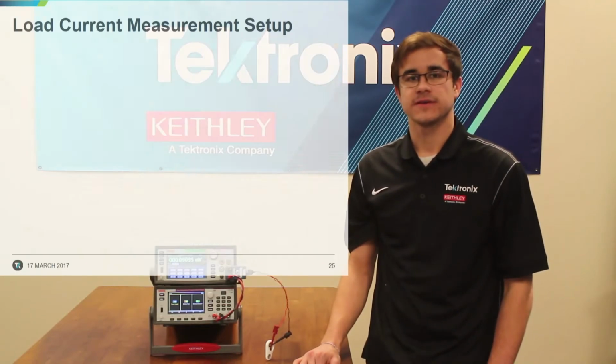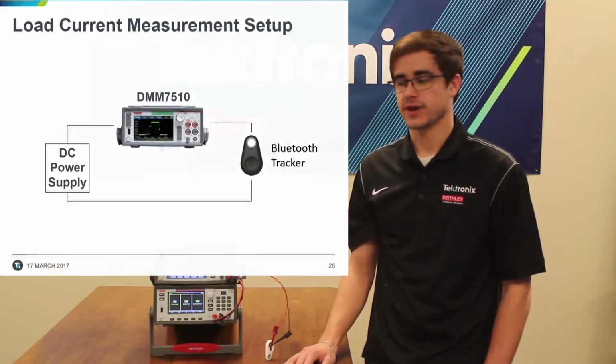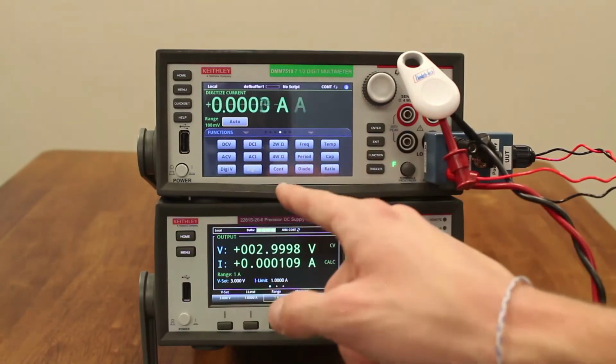I will now show you how this can be done using the DMM7510, the Keithley 2281S precision power supply, and a Bluetooth low energy tracker. With the device attached to this test fixture and the power supply set to source 3 volts, we will now change the function to digitizing current.